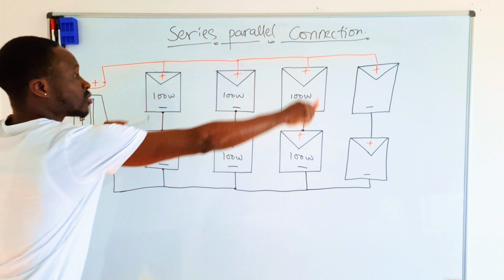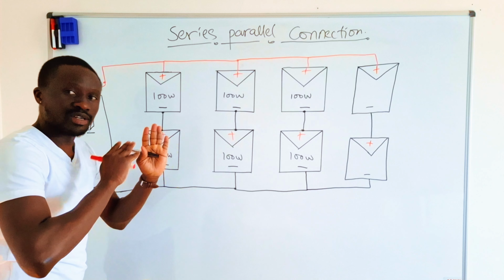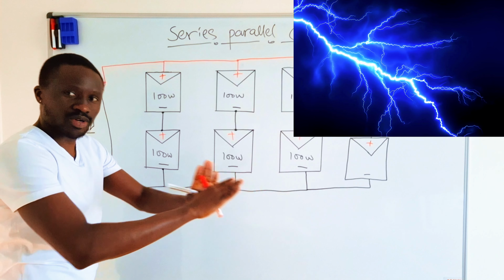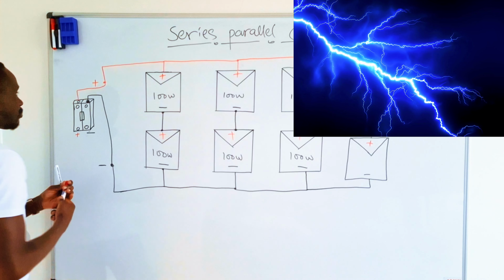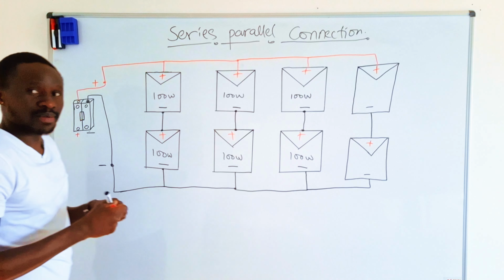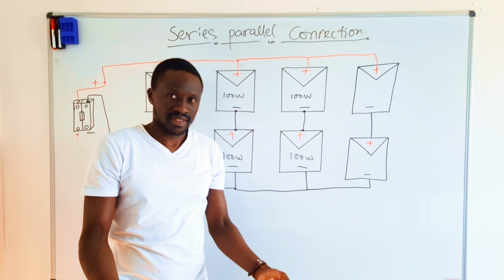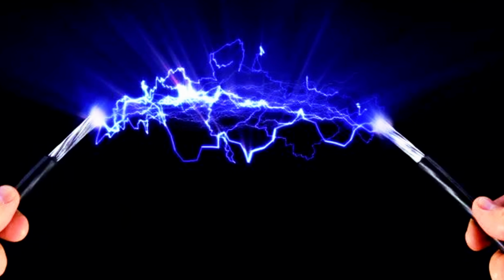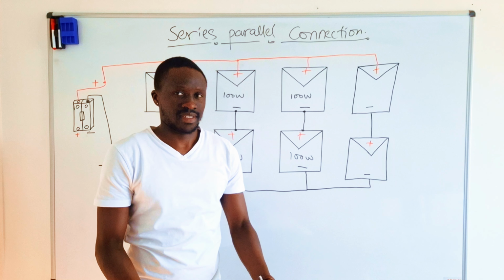Okay? These panels, after installing them, they will produce power automatically. Whereby this power, before we control it, may shock us. Okay? You may install 10 panels, and the moment this cable hangs around the house, it is having power, high voltages, which are DC, high currents.